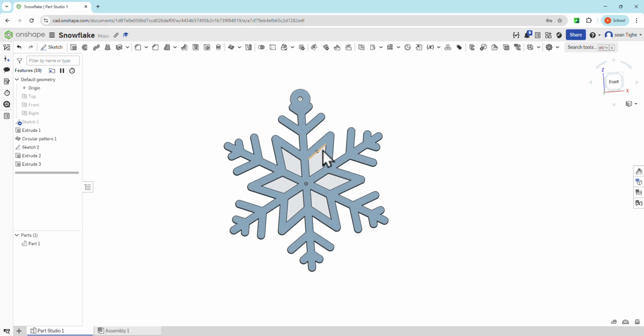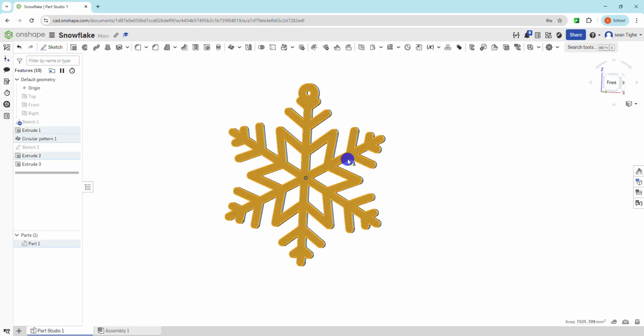So how do we export? To export, we don't select the face first. First up, we turn off all sketches. Turning off the sketches is really important because, as you can see here, when I select this, it doesn't select this area. That's because it's seeing this sketch as being a boundary. But if I hide that sketch, and now I select that face, it becomes entirely selectable. That face there is what I want to export as a 2D drawing.